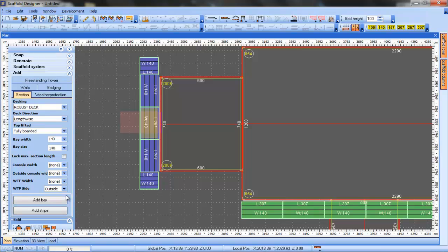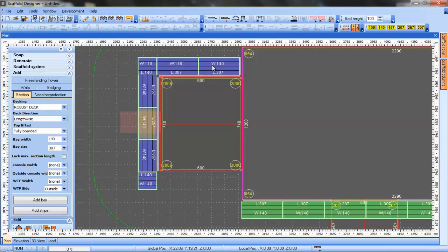And let's continue with the side building. We will place each section like so, being sure to place the guardrails on the outside. We don't need to be concerned with the gutter line or the roof line because the system will take care of this afterwards. We will continue building our stripe by using the bay function. And we will align the bays like so.